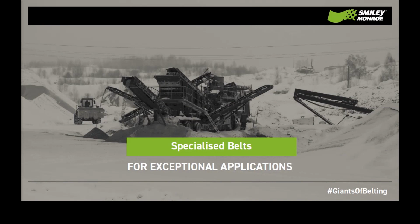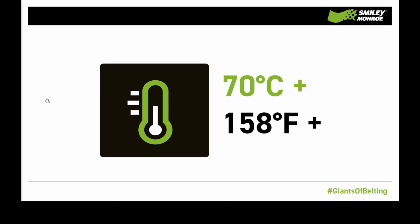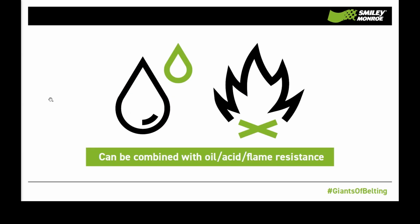Thanks, Ryan. Smiley Monroe can also supply specialised conveyor belting, such as heat, cold and frost, oil and flame resistant belts. Standard belts will crack or delaminate much beyond 70 degrees Celsius or 158 degrees Fahrenheit. High temperature belting increases belt life through special fabrics and compounds available for extreme temperature applications. This type of belt is used to convey clinker, coke, foundry sand, ore and slag, or any material above 70 degrees Celsius or 158 degrees Fahrenheit, and it can be combined with oil, acid or flame resistance.